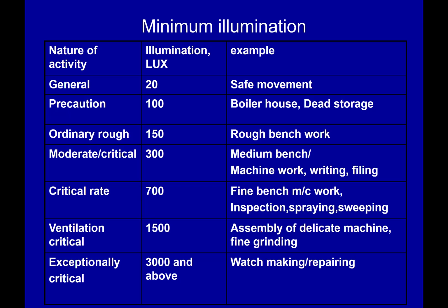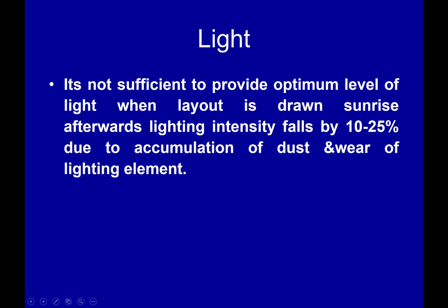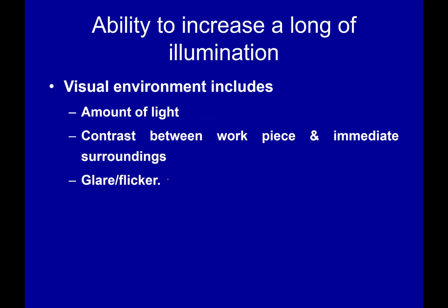So this is about the different kinds of things about which I have already talked. It's not sufficient to provide the optimum level of light when the layout is drawn. Why? Because the light intensity falls 10 to 25% due to accumulation of dust and wear and tear of the lighting system. So it's not like we should forget after installing the required lighting systems.